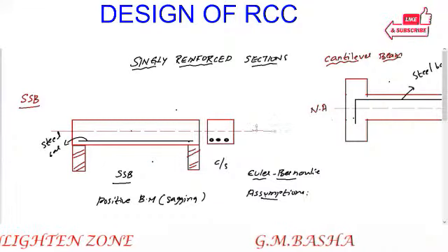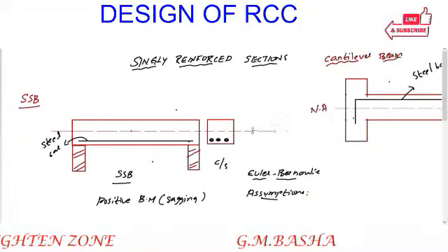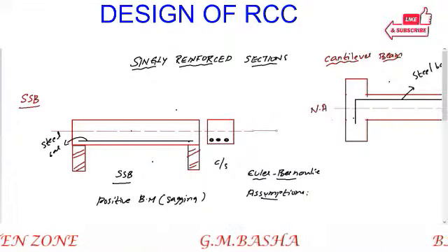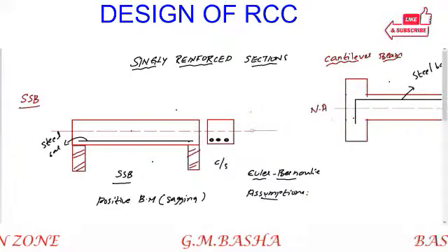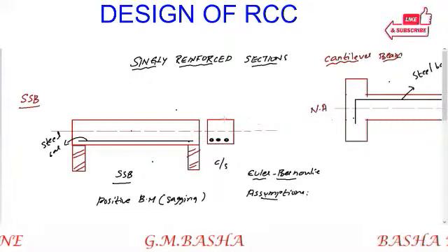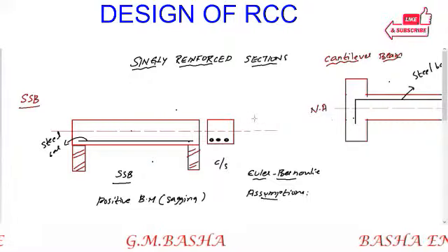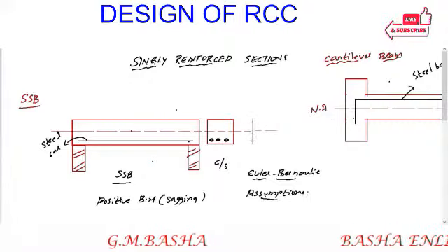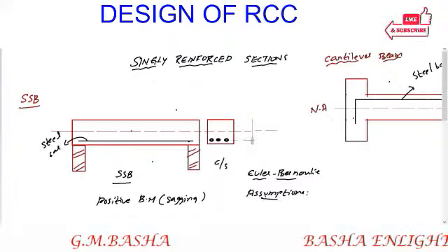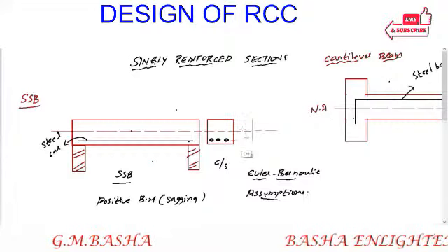So I am drawing the strain diagram. Based on this, there will be some assumptions. This is the neutral axis. Here I am drawing the strain diagram as a continuation of this member, up to the tension reinforcement only. This level is up to there only.